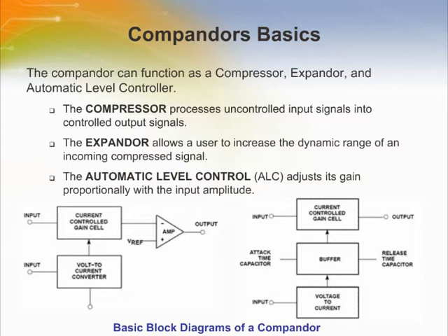There is one basic reason to compress a signal before sending it through a telephone line or recording it on a cassette tape, and that is to process the signal, be it music, speech, or data, so that all parts of it are above the inherent noise floor of the transmission medium, thus avoiding running into the maximum dynamic range limits, causing clipping and distortions.